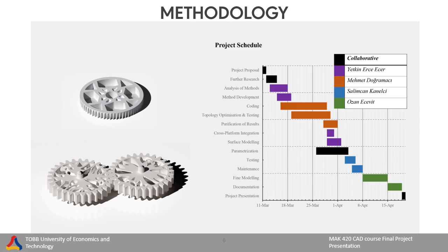For commercial products, we begin with creating a CAD model based on specific dimensions. Next, we optimize the gear design using topology optimization algorithms, adjusting the material layout. We refine the optimization using Bezier surfaces to streamline further design and manufacturing processes. Finally, we generate an STL file for the final design.